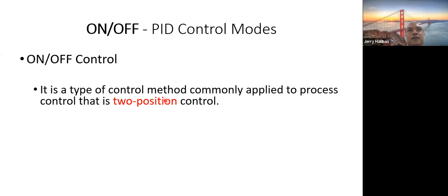So after, let us say, about 10 years ago, after using that control valve, its position was always either fully open or fully closed, so it wore out. That is normally the lifetime of a pneumatic control valve, as long as it's properly maintained.